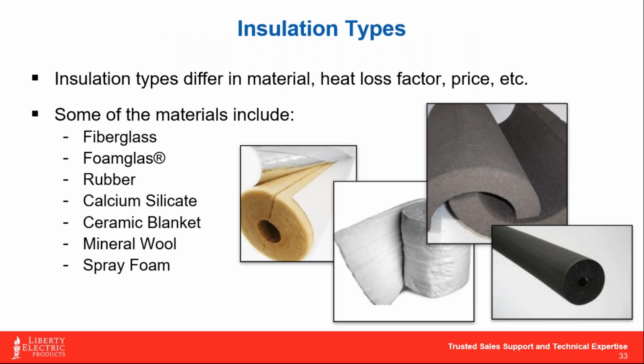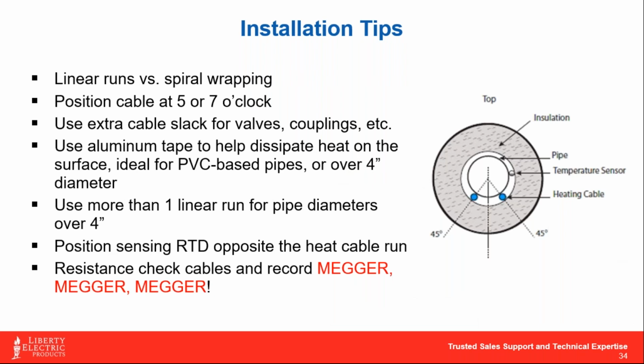Just a couple more slides here. I know that we're basically to our point here, but here are a couple of your common insulation types. In most cases, I don't think you need to get anything exotic on there. As long as you've got at least an inch of insulation, and what we shoot for is an inch to an inch and a half, that will usually take care of you just fine in most of these applications. And once you start getting over an inch and a half, it starts getting pretty expensive anyways.